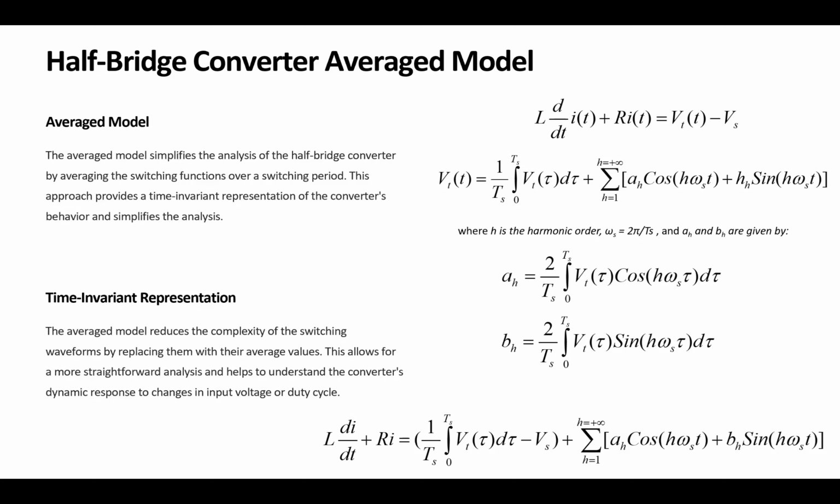Now, the last thing that we talked about in the previous session was the mathematical model that we could have for a simple half-bridge inverter when it works to deliver power to our AC system. We ran a KVL over our circuit, if you remember, and we came up with this differential equation, based on the KVL in the equivalent circuit model that we developed.